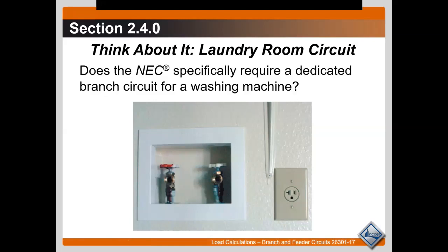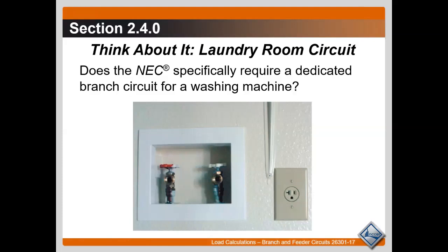First and foremost, if there's a sink in there and you plug in a phone charger or whatever, or like my wife does, she puts a cordless phone in the laundry room. What if it falls in the wash basin while she's hand washing the clothes? Especially if it's not GFI protected. You can't put a GFI receptacle there because that machine motor will trip the outlet right in the middle of your wash. It'll be a frustrating scenario. So that's why the single outlet. Just keep that in mind.